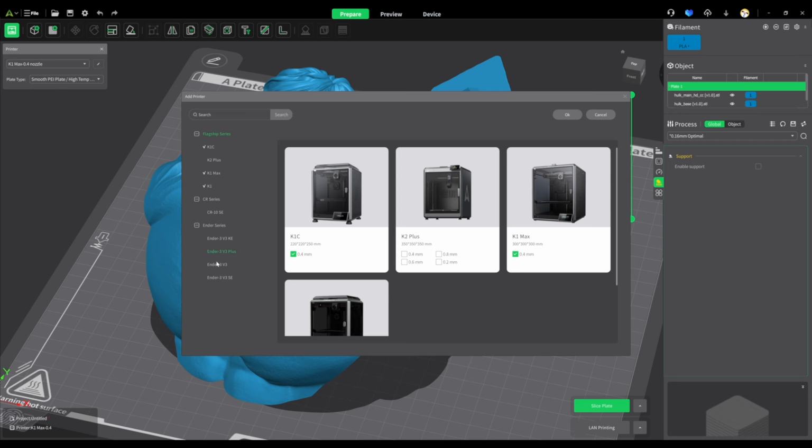If you are trying to use adaptive layers with organic support, it's not compatible, and Creality Print 5.1 does not tell you that, okay? So another big issue, it's not actually a bug, but it's like a Creality lazy manifestation about their software, is that they still have no profiles for all the Creality printers inside the Creality Print software.